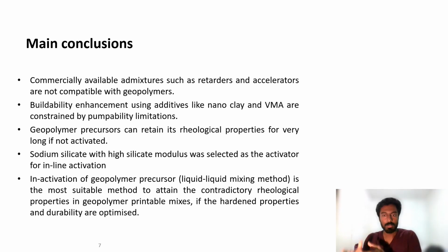And once that is sent to the printhead, you can activate using the activated solution, and get the buildability which you want. So you can have both high open time and good buildability without using chemical admixtures like set retarders and set accelerators.